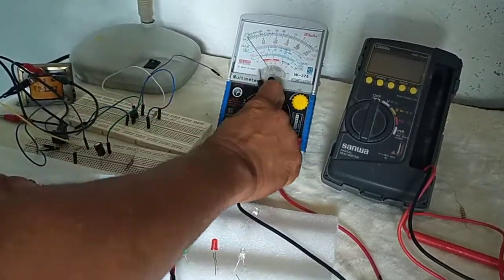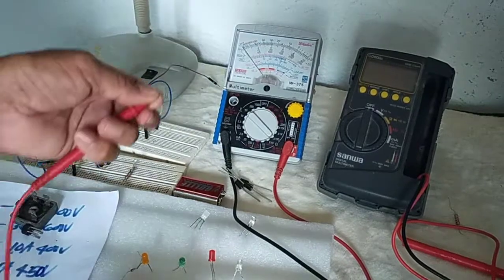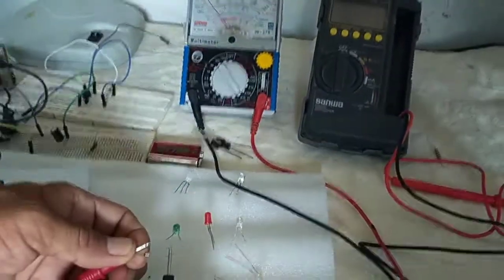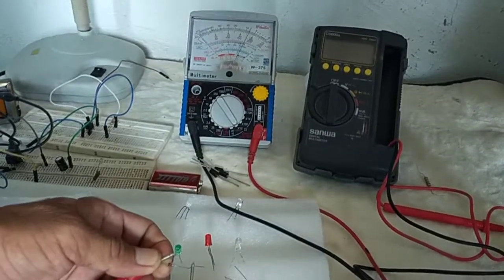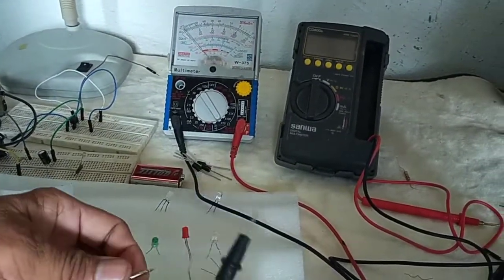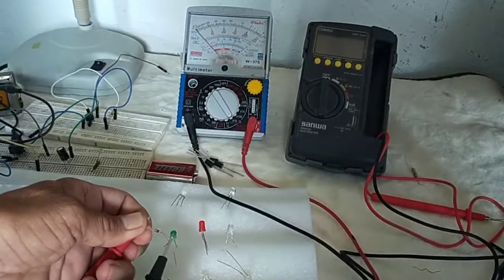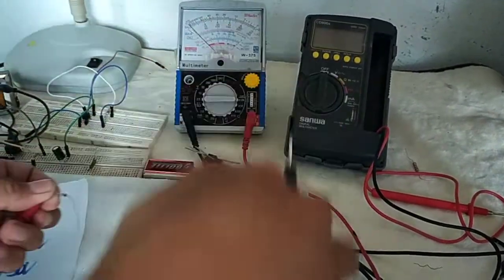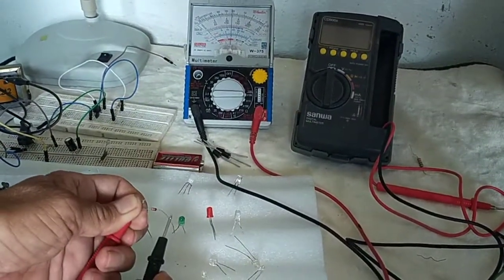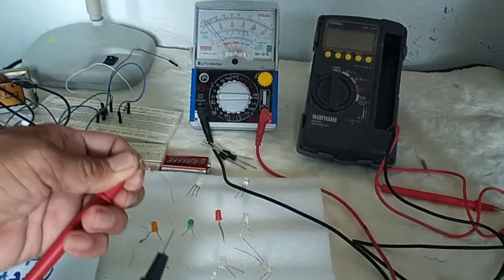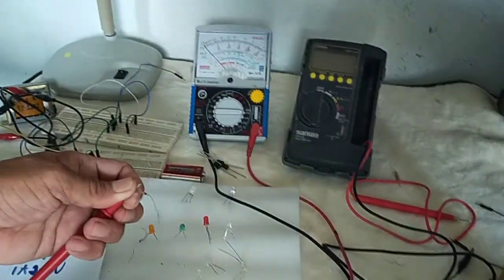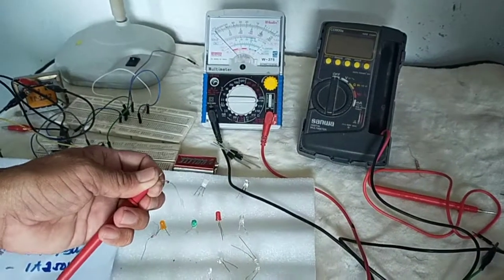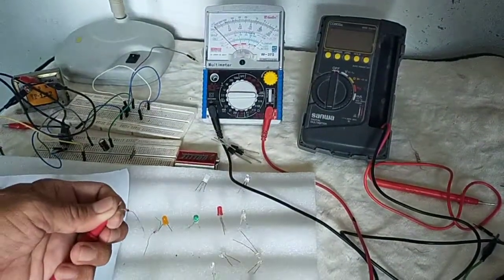But for the other Zener diodes, for example this one, let us try. Using times 10 ohms, it deflects in forward bias. When it is reversed, there is no deflection. But when you are using times 10K as the highest range of the ohmmeter, there is deflection. So you might think it is defective or leaky because in the reverse direction there is deflection of the pointer. No, that is normal for the Zener diode.